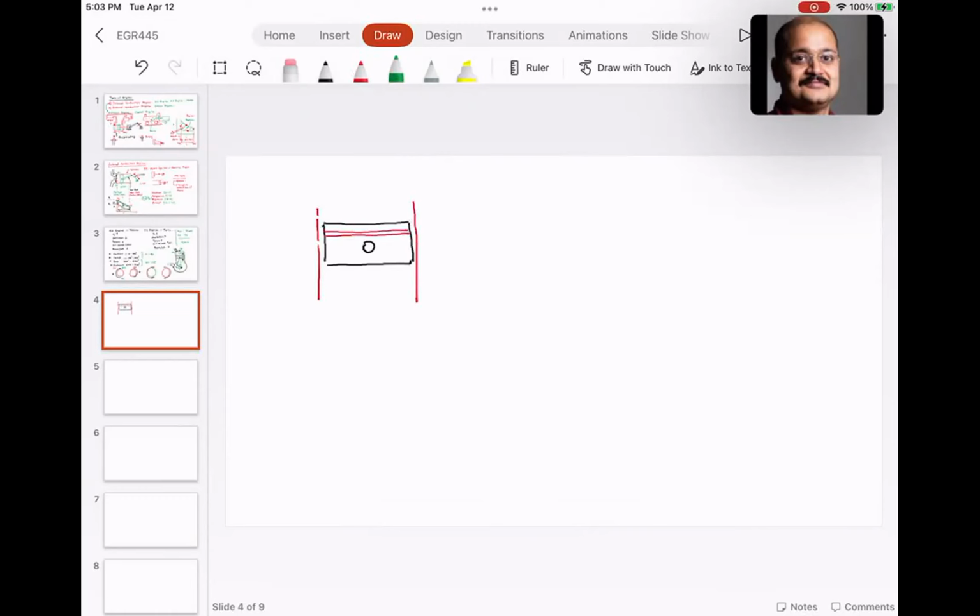And in these grooves, there are rings. These are called piston rings. There could be one or two. At the end, there is something called the oil ring. The purpose of the oil ring is basically to scrape the oil off the cylinder wall.